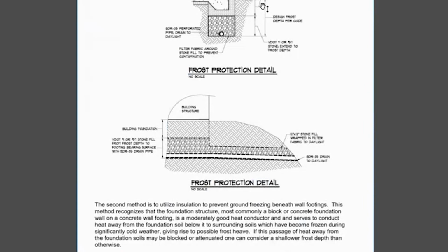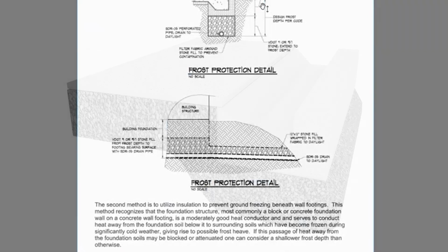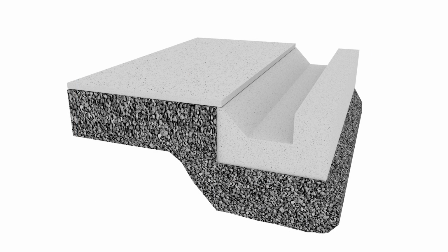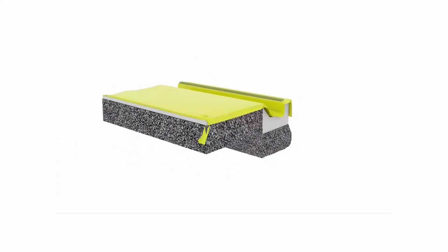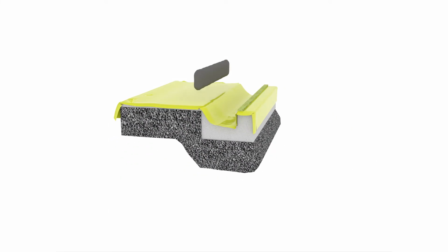And that gravel acts the same as it would be as if we were putting some kind of a foundation and a footer system in. Out here, this is the Build Smart high-performing J-form assembly. It does not allow heat loss from the building. So therefore, there has to be a whole other approach as to whether wing insulation is required or not required.